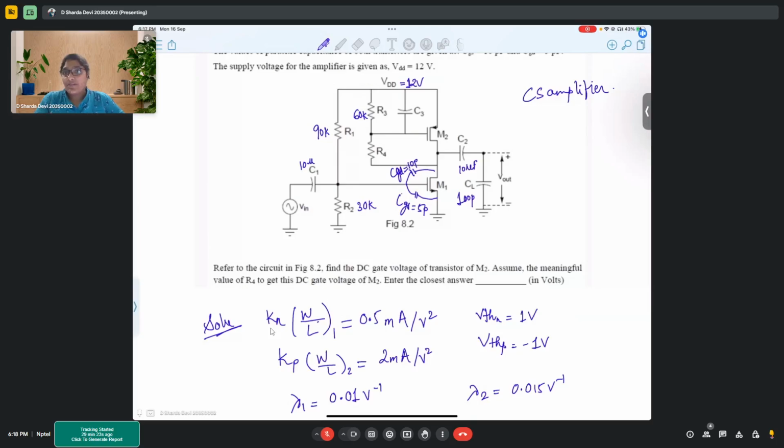But when you talk about resistors, you imagine that the wire thickness you would need is still quite high. Getting a 60 kilo ohm resistor, how big would that resistor be if it is a wire-wound resistor? That's not feasible for an IC, right? So we try to design the circuit with small components, which are the transistors. The whole circuit is made up of transistors. That is the basic idea. Even capacitors we draw out of them.